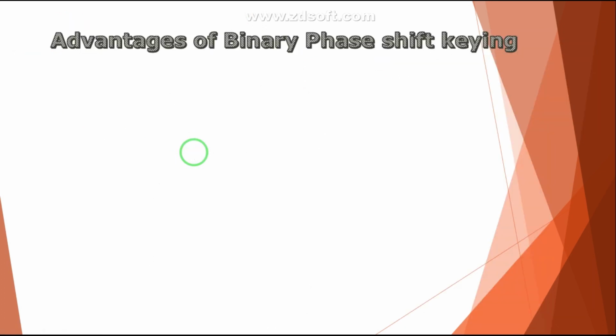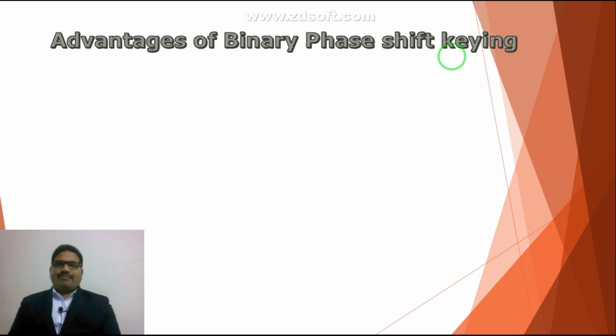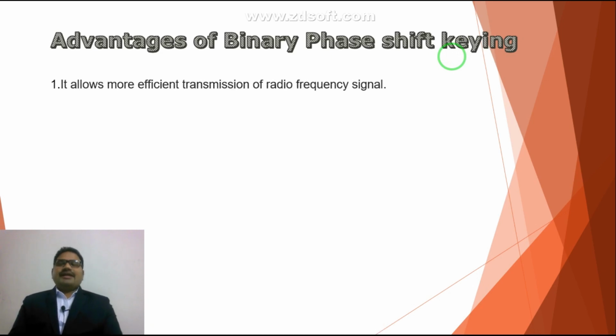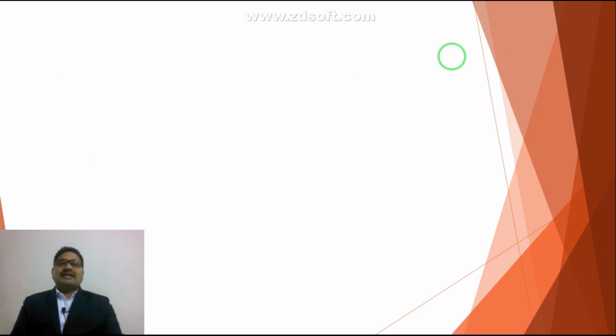Now, what are the advantages of binary phase shift keying? It allows more efficient transmission of your radio frequency signal. Better noise immunity is noticed as compared to amplitude shift keying. And third, less bandwidth is utilized by the BPSK signal in comparison to the BFSK signal.